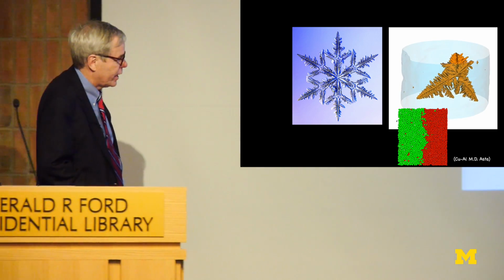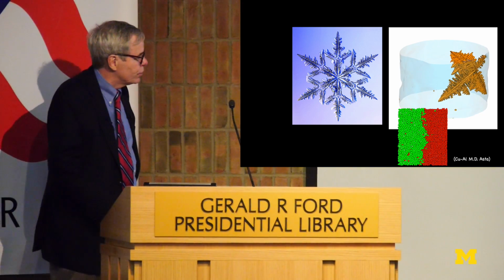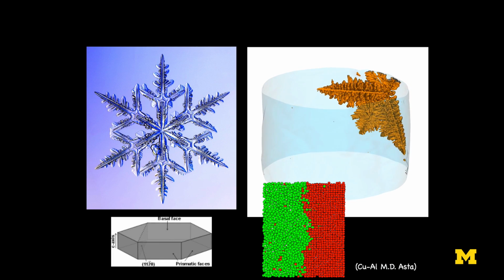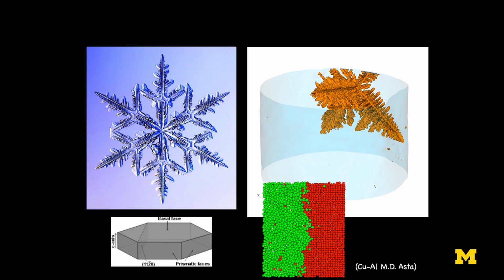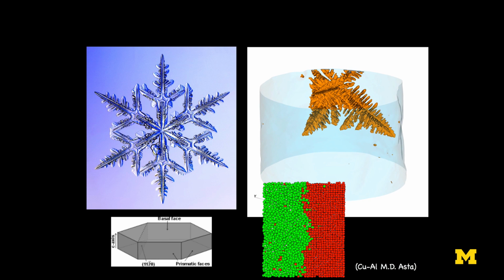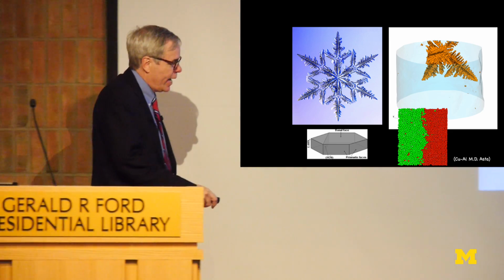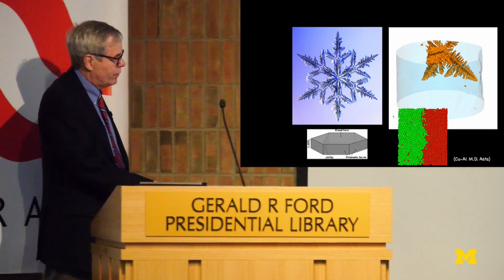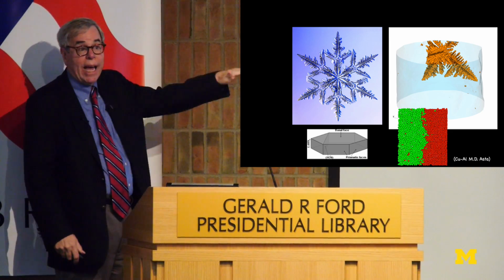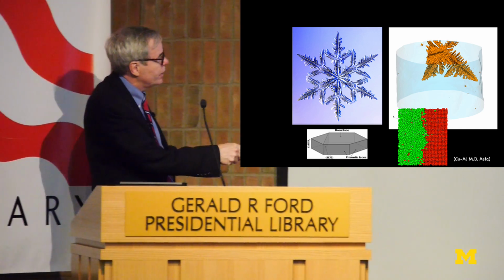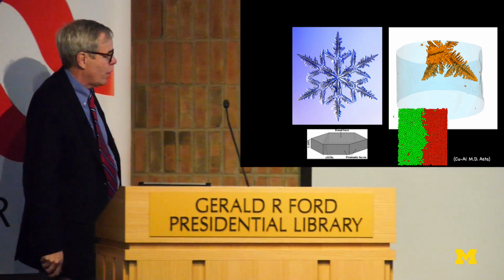It can find places to stick. If you look at this structure, it's actually what's called a facet, and this is the crystal structure of ice. It's hexagonal. This is the face. The basal face here is what's actually on the face here, and it's very hard for atoms to attach to the face of this crystal because it's atomistically flat. Whereas on the sides, it's atomistically rough, and it can grow these nice secondary arms.